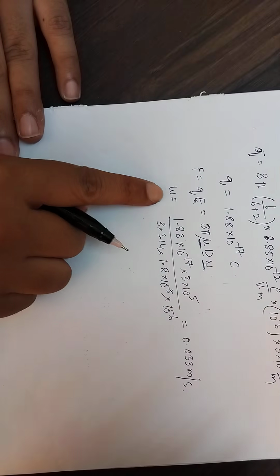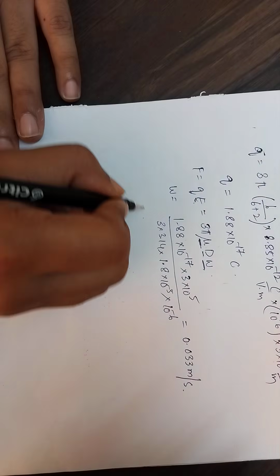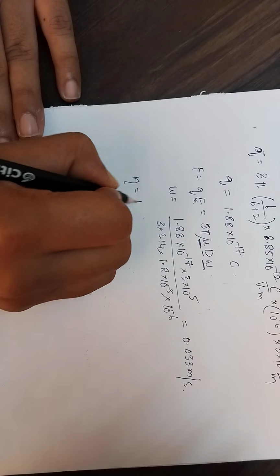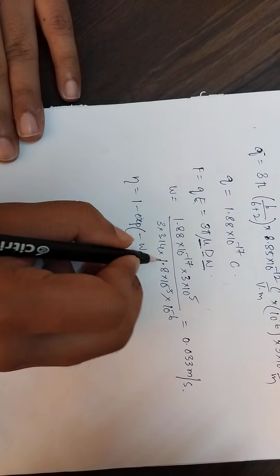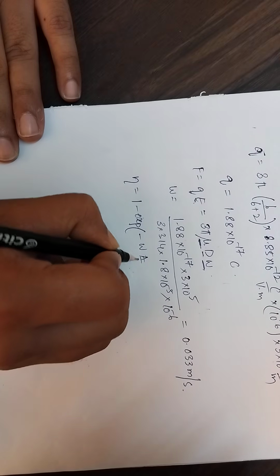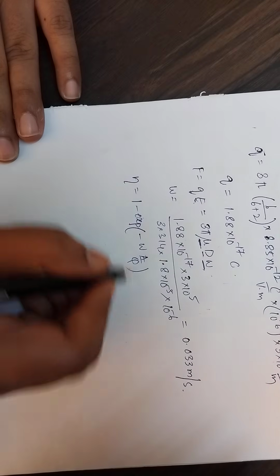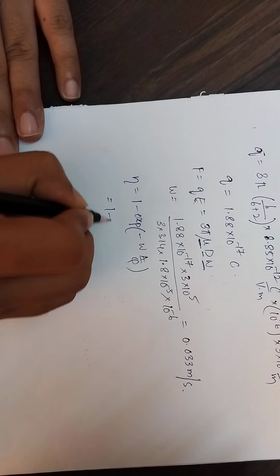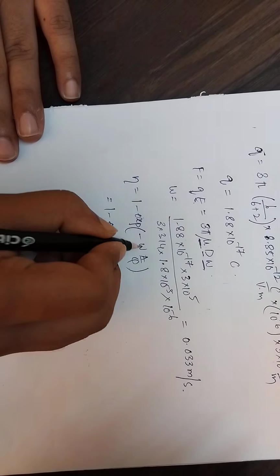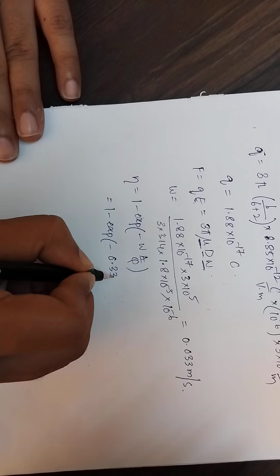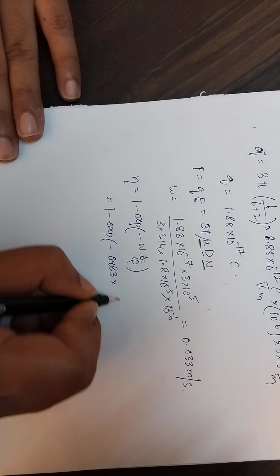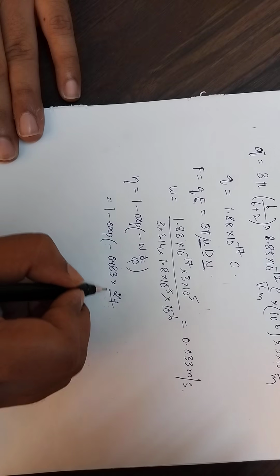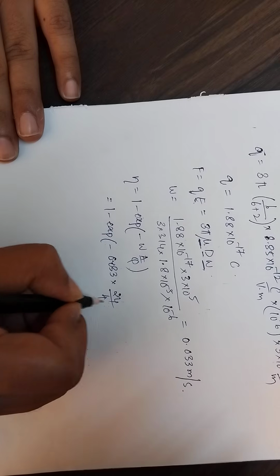Once we have the drift velocity, we can calculate the efficiency. Efficiency is basically 1 minus exponential of minus migration velocity or drift velocity into A by Q. A and Q values are given, just substitute 1 minus exponential of minus W, which is 0.033, into A by Q. A by Q is 24 by 400.